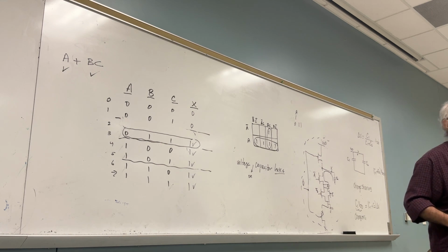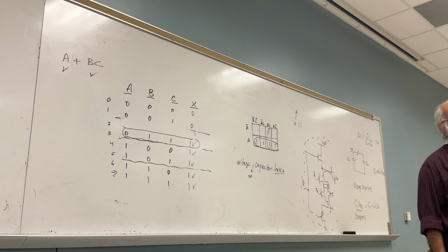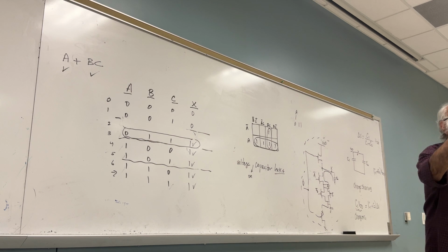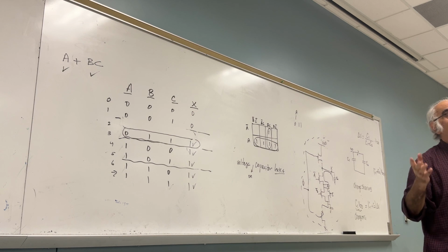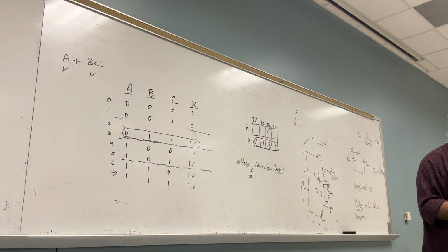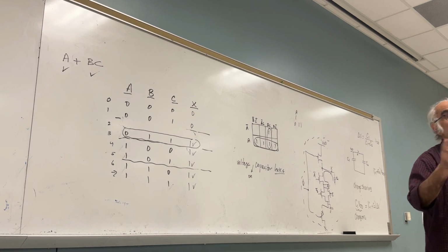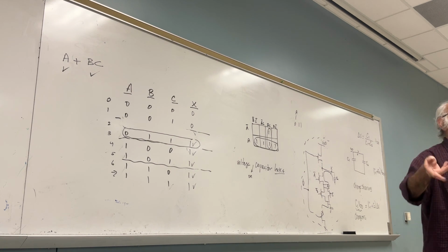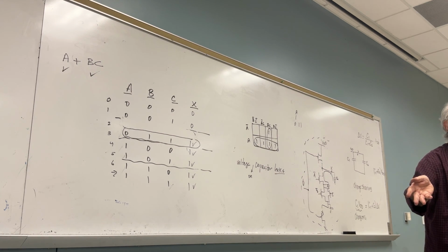Let's not worry about the value. Are you telling me the voltage across C1 and the voltage across C2 is what? It's not the same because the NMOS does not pass a strong what? Strong one. A strong one.